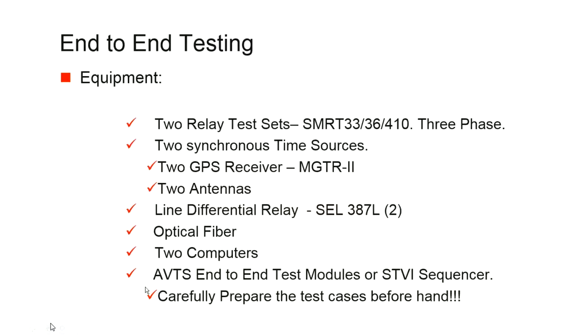My take in all this is this last line here. Carefully prepare the test cases beforehand. Don't improvise, and understand fully the system that you're going to test before you go into the substation to do your testing. If not, you're going to end up wasting and losing a lot of time.